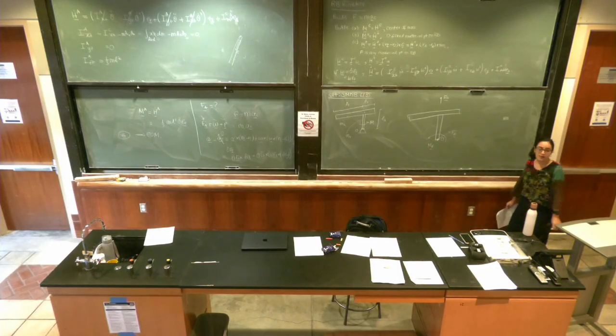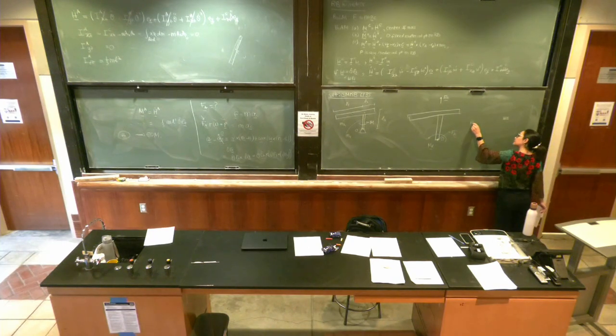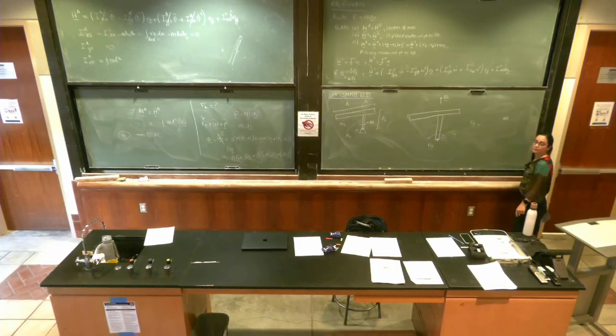Now, because, what is the direction of the reaction force? Yes, exactly. Why? The direction of the reaction force is along X, Y, and Z in all three directions, because the motion of the base is restricted along all three directions. I cannot translate the base along any direction. So FR is going to have X, Y, and Z components.